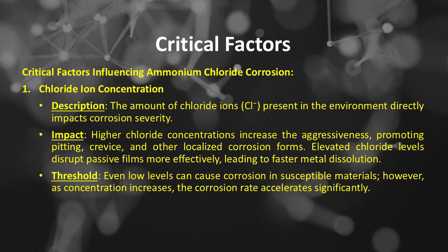Description: the amount of chloride ions present in the environment directly impacts corrosion severity. Impact: higher chloride concentrations increase the aggressiveness, promoting pitting, crevice, and other localized corrosion forms. Elevated chloride levels disrupt passive films more effectively, leading to faster metal dissolution.